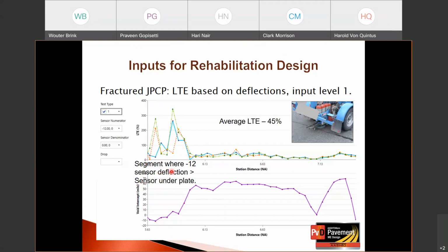This first segment is also where we have the hard layer closer to the surface, but we do have hard layers closer to the surface within these other segments. But there is something else going on within this pavement structure that there was insufficient data to try to identify what's causing this specific condition between segments 1 and 2 versus segments 3 through 6.